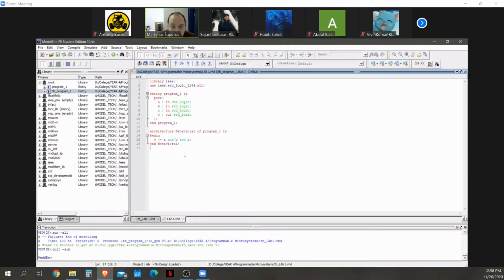Here is nothing. Here is just a part of concurrent logic. Here should be a process like in my example. And for now, you just added a simple assignment in concurrent logic. So you should do it inside the process, and you should model two processes, not one. So first of all, you have to make two outputs, y1 and y2, for example, which will be both outputs. Okay. And another part, you should put the assignment statement where I is equal to A and B and C.